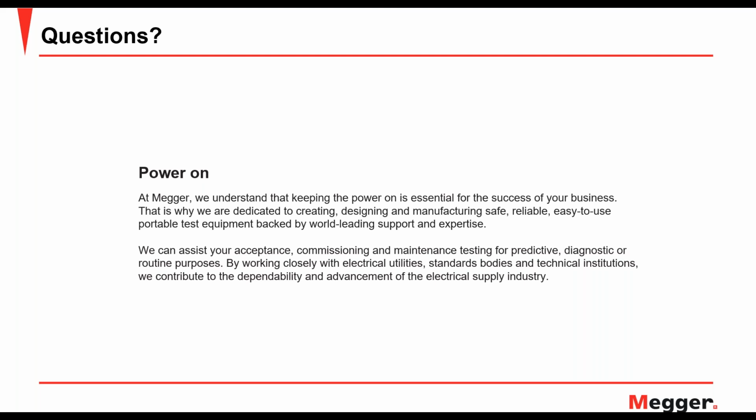So in an ideal world, if you had a winding resistance instrument that had the ability, and you had confidence in its ability to fully demagnetize the transformer core, then it would be nice, before you do your SFRA test, to demagnetize it with that instrument and get it into this precise neutral state. And then next time you do your SFRA test, again demagnetize the core and then do the test, because that way I've got this in a precise neutral state.